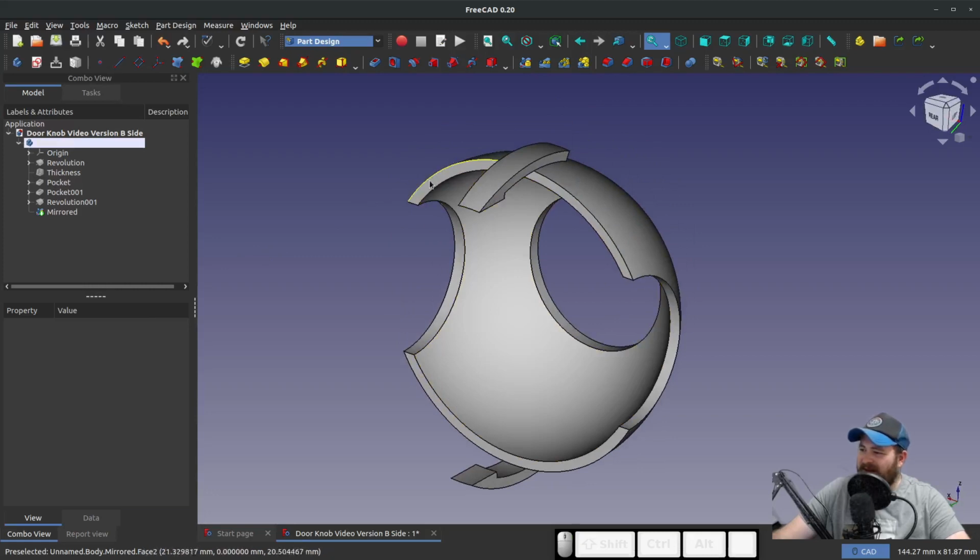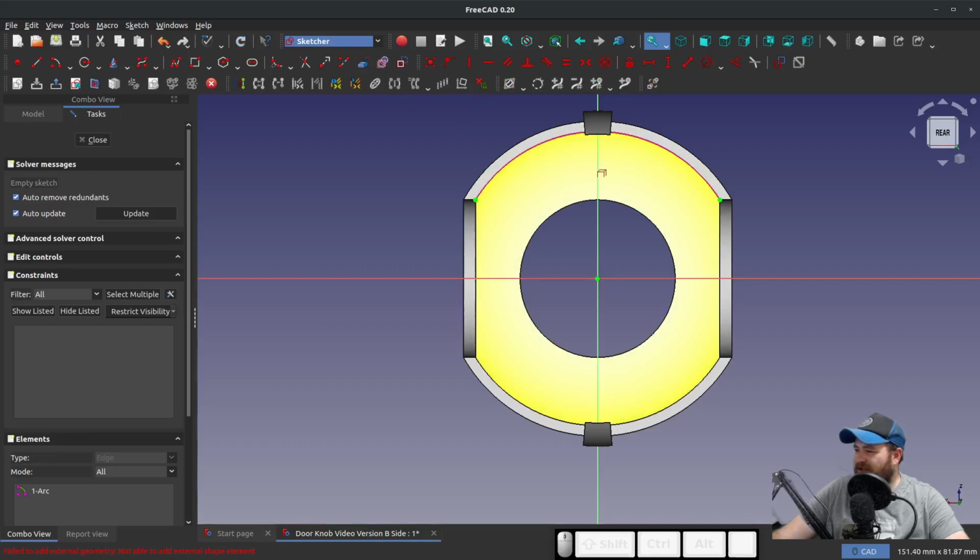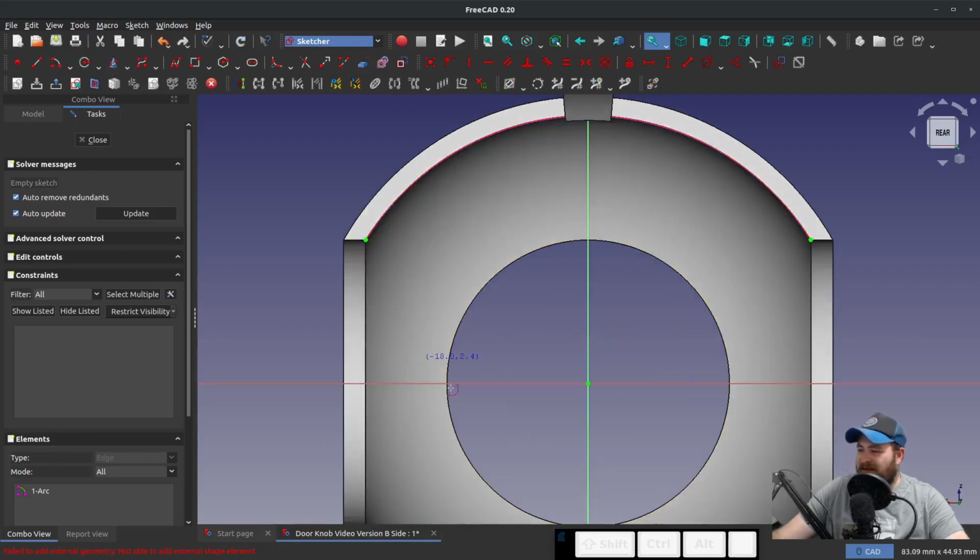We want to adjust this face because we have a groove on the other side, so let's make a tongue on this side. For that, I'll create a sketch on the highlighted face. We'll import, where's my import? There it is. This edge here. And I can use my origin and endpoints of that edge to make an arc. Make a second arc.